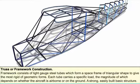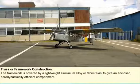The framework consists of light-gauge steel tubes welded together to form a space frame of triangular shape to give the most rigid of geometric forms. Each tube carries a specific load, the magnitude of which depends on whether the aircraft is airborne or on the ground. It's a strong, easily constructed and relatively trouble-free basic structure. The framework is covered by a lightweight aluminium alloy or fabric skin to give an enclosed, aerodynamically efficient load-carrying compartment.